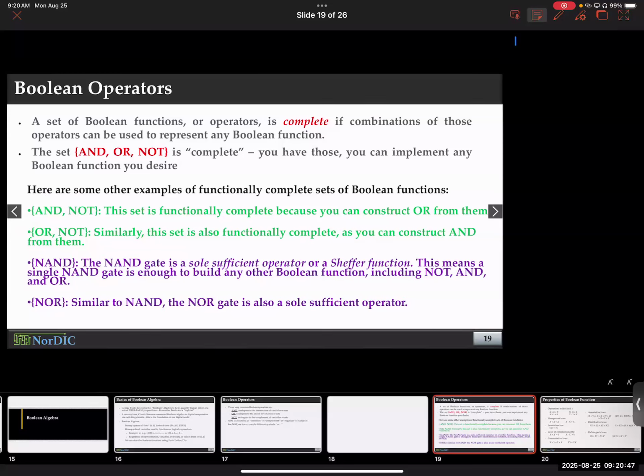You can represent any Boolean function with NAND gates, only NAND gates, if you don't have any other gates. But it's not going to be the most optimized. And what do I mean by optimized? In terms of speed, in terms of area that is necessary, in terms of power demand, it's not going to be the most optimum design. It will work functionally, but it will not be the most optimum. But if you bring more gates to the mix, like NAND, NOR, invert, XOR, and so on, the more things you bring to the mix, the more optimization opportunities you will have.